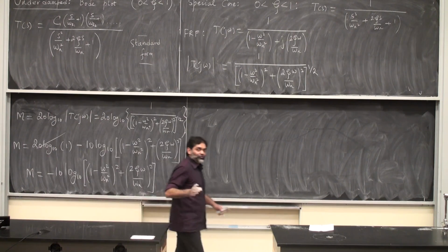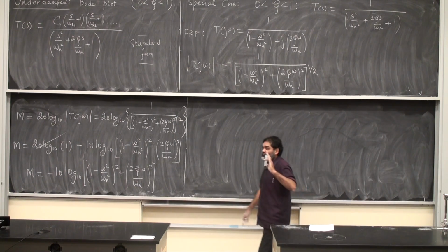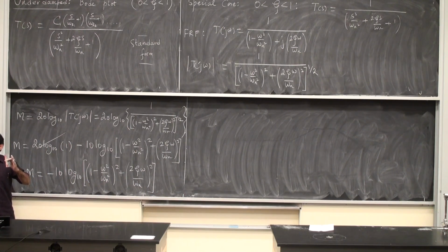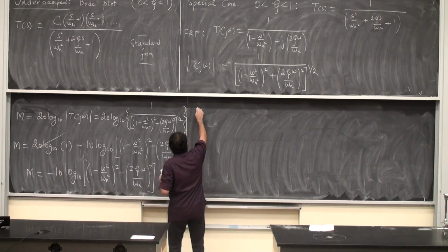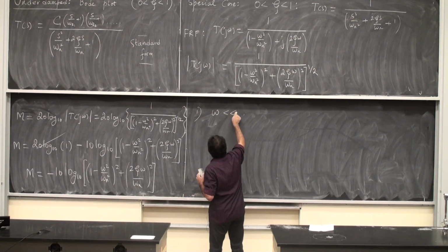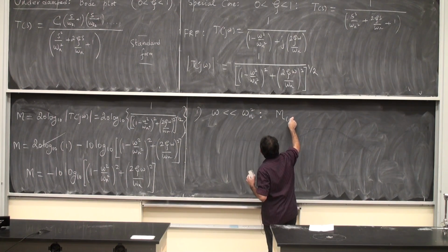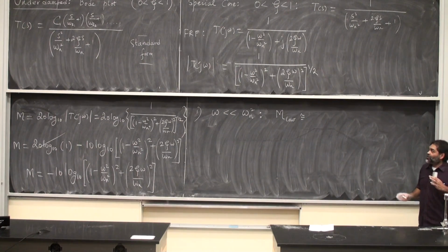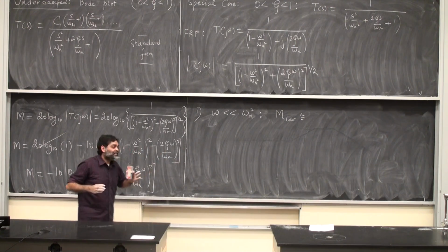Exactly the same approach as before. Okay, there is nothing special here too. Asymptotic analysis. Here your corner frequency, if you have the underdamped system, is going to be your natural frequency. Okay, so that's where the special action takes place, resonance and all these kinds of things. So for omega very small compared to omega n, you see what happens?